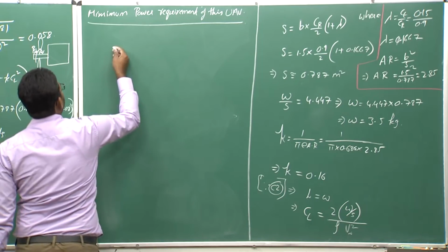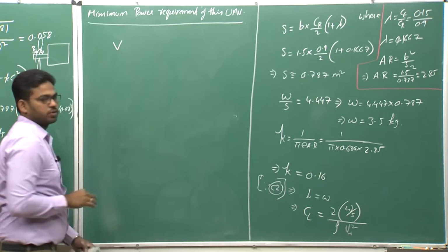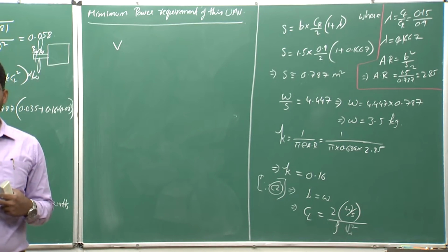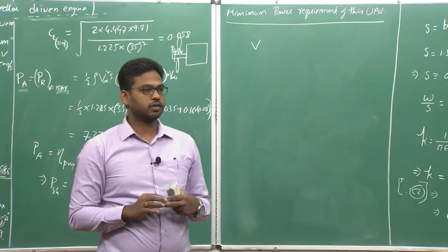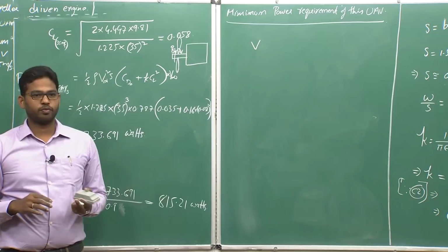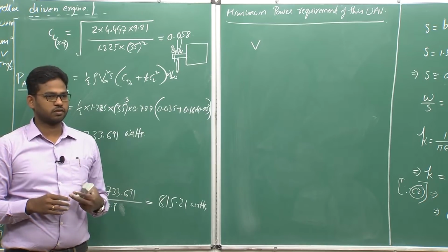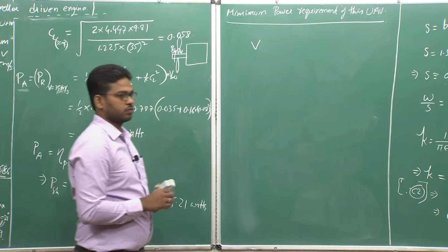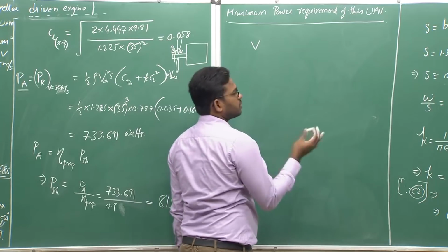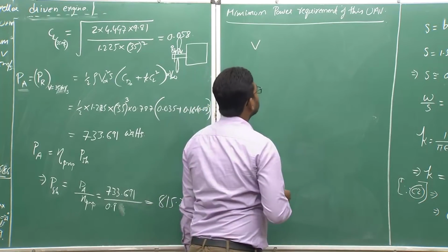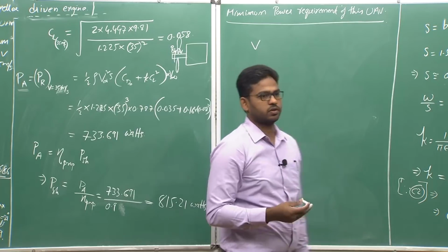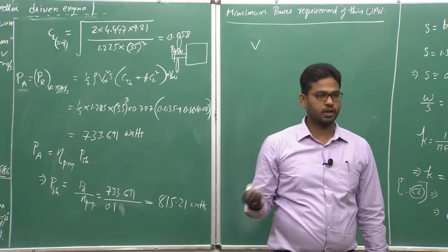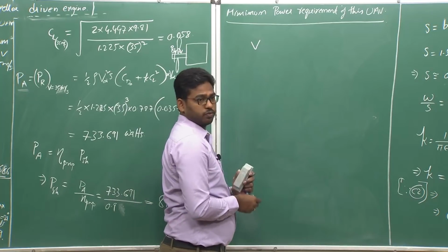You need to first find what the velocity should be, right? So, do you know the range of velocities that you can fly? What should be the range of velocities? Either the velocity for minimum power required or the stall velocity, right? And the upper limit is the maximum velocity that you want. So, let us find out the lower limit of this velocity range. For that we need to find out two velocities: both the stall velocity and the velocity for minimum power required.